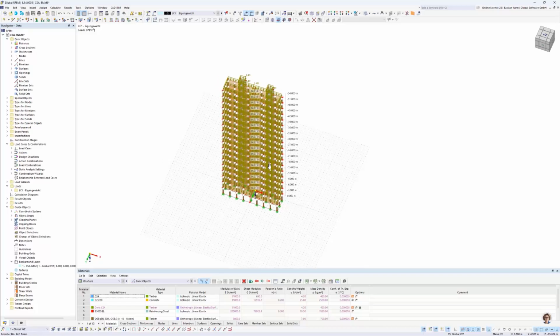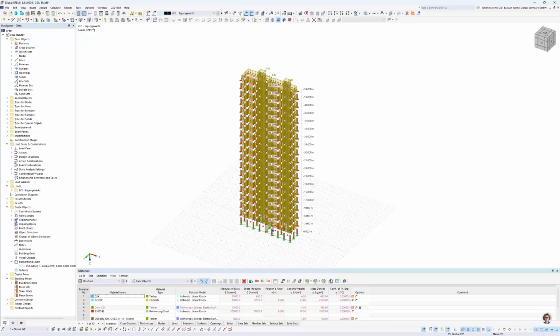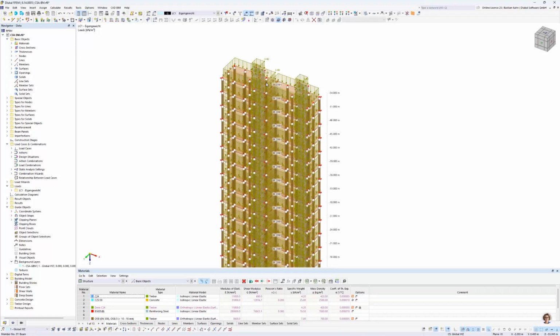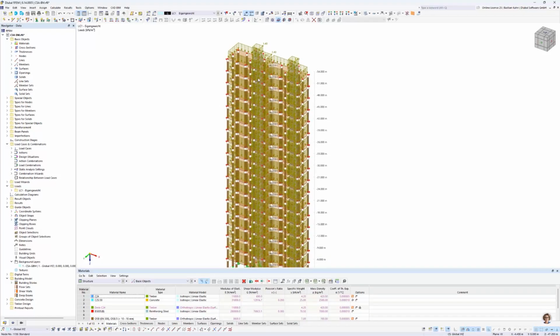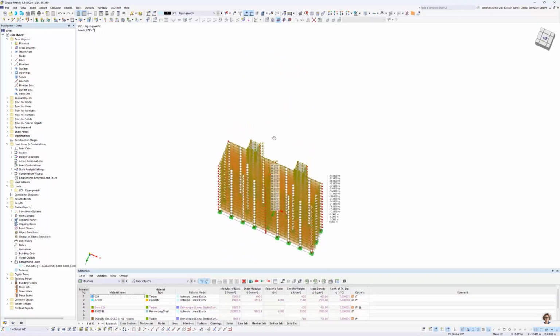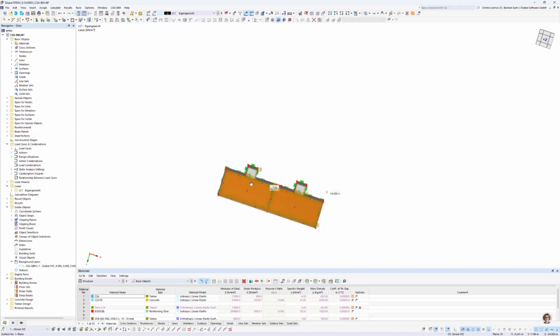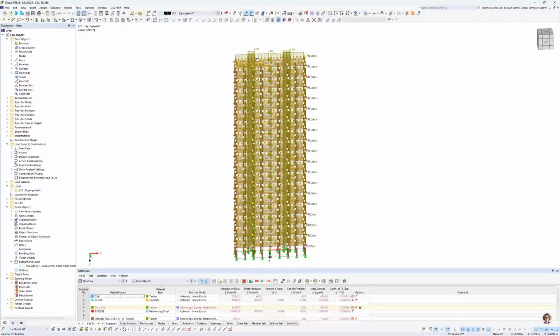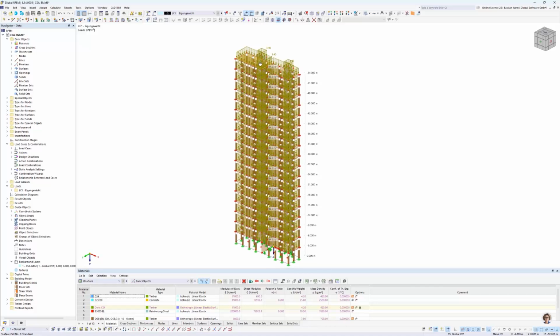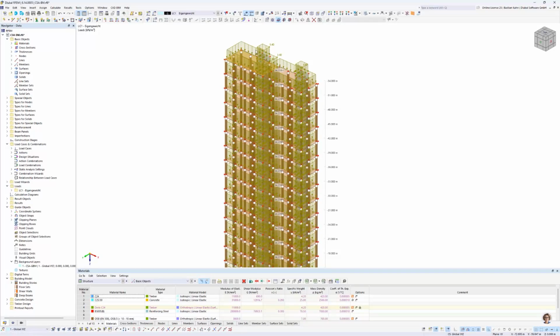As the modeling process is solved already, we can switch off the grid and take a first look at the results. Yeah, I think I said it, but just to focus on it again, this is missing the columns in this point, and also this point. And so I expect quite a high loading in here.